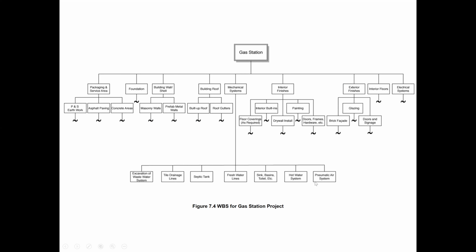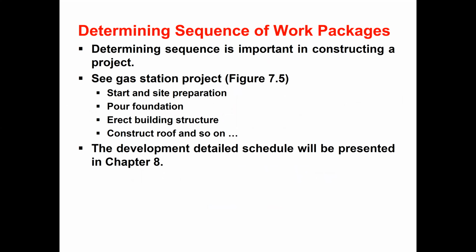So this is the way that first we should break down our structure and prepare the WBS, and then after having the WBS, we should build the schedule. To prepare a schedule, first we have to enter the WBS in Primavera. What is the project information, start date, and things like this. Project information. Then we decide the WBS. Under the WBS, we will enter the activities and their durations, and then we prepare the schedule.